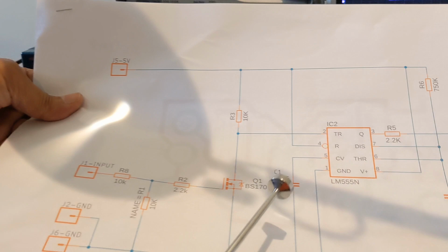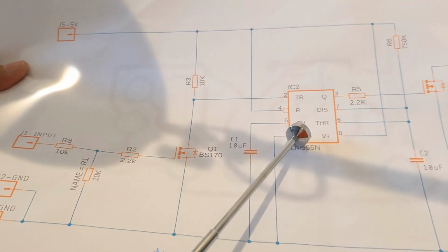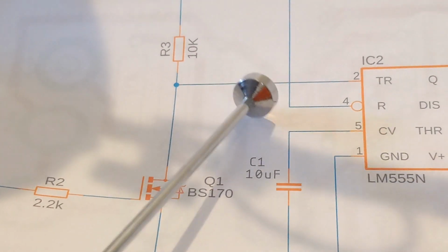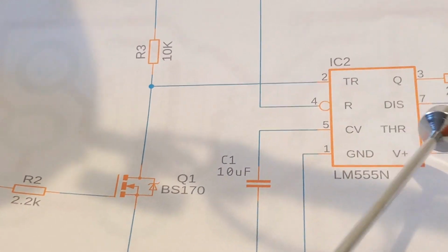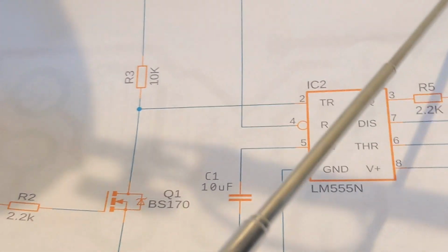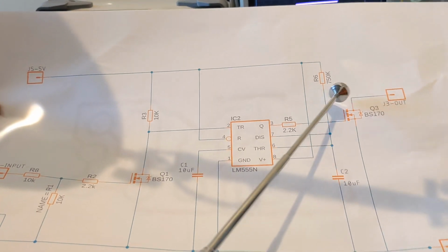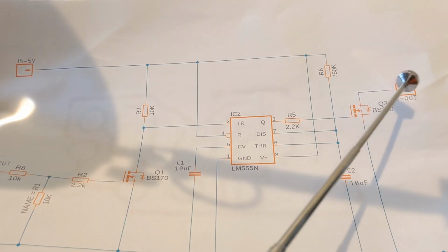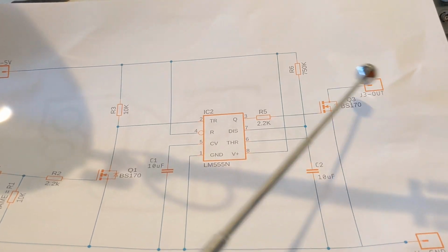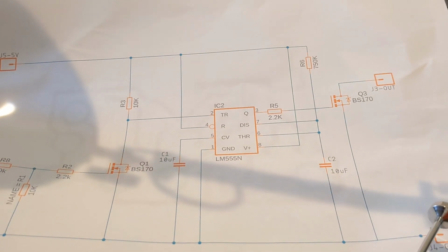This is accomplished by using a 555, and you just trigger that in fixed duration by this resistor and that capacitor. I'm putting a transistor here so I could get isolation, just to get a sinking output.